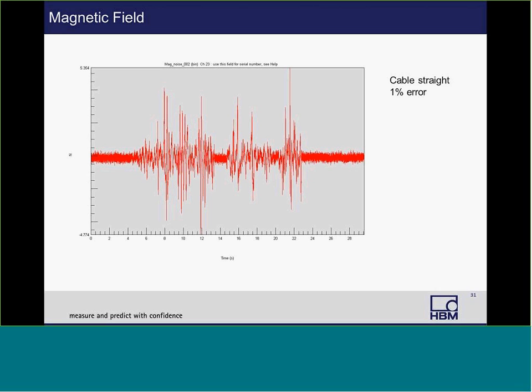This highlights how important cable routing is. It's always best to have a cable the exact right length needed. Now, that's not always possible, especially if you have a load cell with a preset length. But the key is you shouldn't coil it up in loops when you have extra.